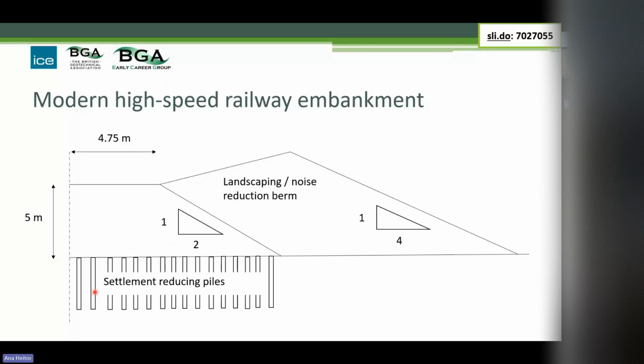The first thing you notice is there's all of this concrete below the embankment. Why have you got this concrete below the embankment? Well, because the maximum allowable settlement is 30 millimetres, and our calculation says it's going to be 32. Really? How did you do the calculation? Finite element analysis. And when did you start consolidation? After we built the embankment.